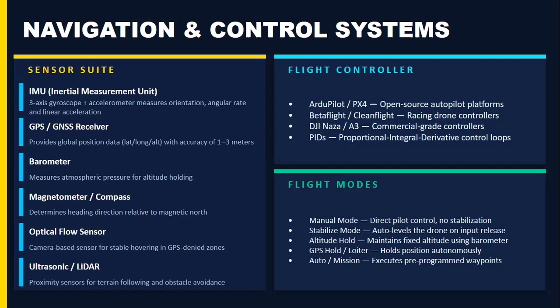Additional sensors such as optical flow cameras, ultrasonic sensors, and lidar sensors improve stability and obstacle avoidance. Flight controllers such as ArduPilot, PX4, Betaflight, and DJI systems process all sensor inputs and execute the control commands using PID algorithms. Different flight modes allow varying levels of automation, from manual operation to fully integrated autonomous waypoint missions.